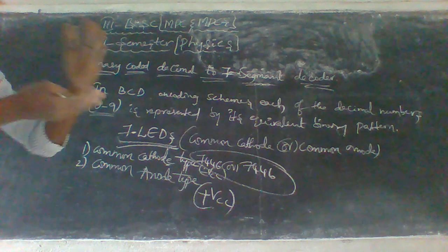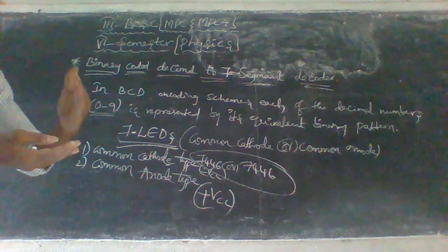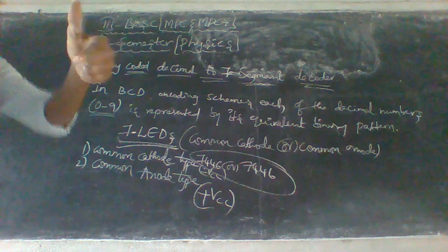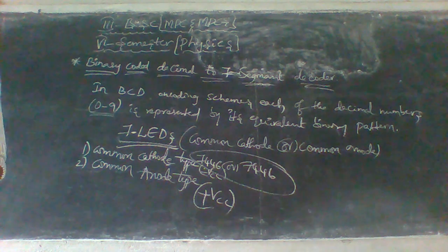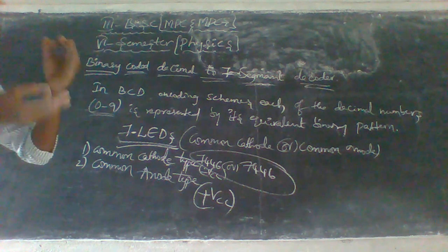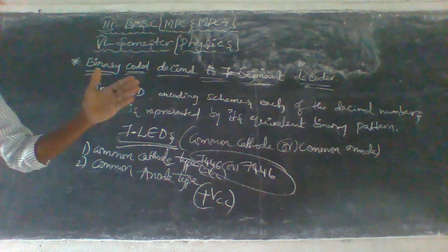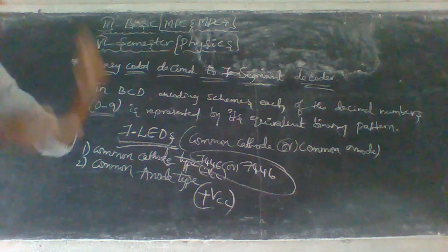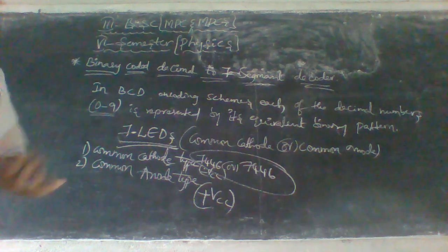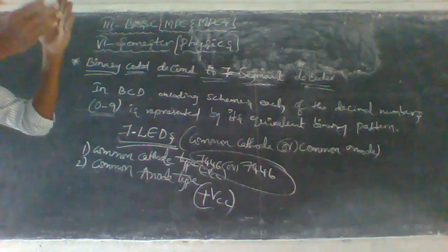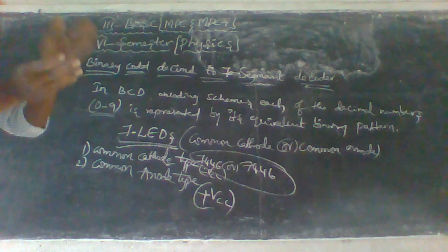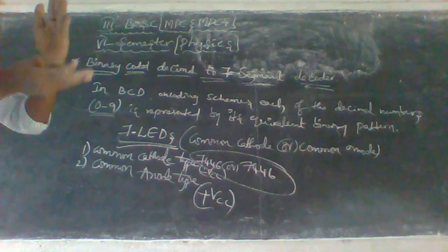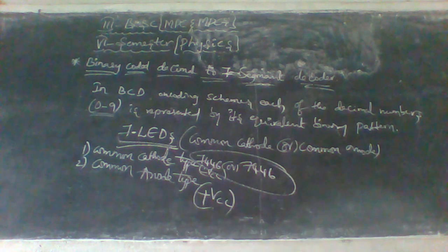But a 7 segment display does not work by directly supplying voltage to different segments of the light emitting diodes. First our decimal number is changed to its BCD equivalent signal. The BCD to 7 segment decoder converts the signals into the form fed to the 7 segment display.